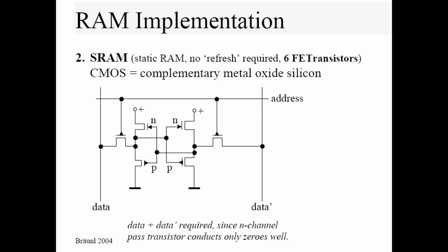As per the operation, we have two: the write operation and the read operation. The word line is activated, turning on the access transistors Q5 and Q6, and the data is written to the cell by driving the bit lines BL and BL prime to the desired values. The cross-coupled inverters latch the new state. So that is for the write operation.